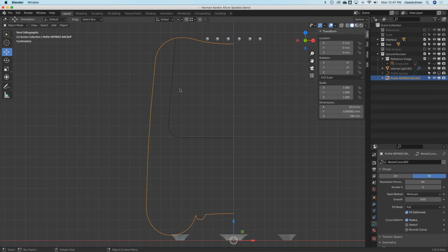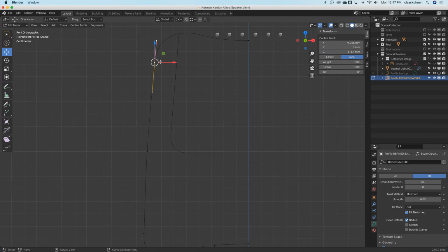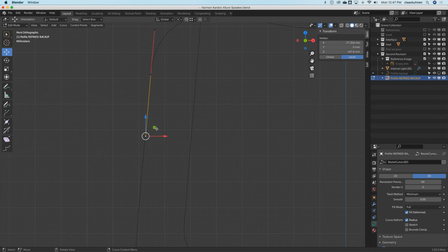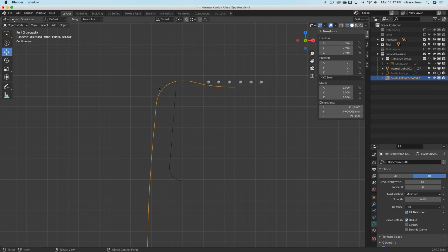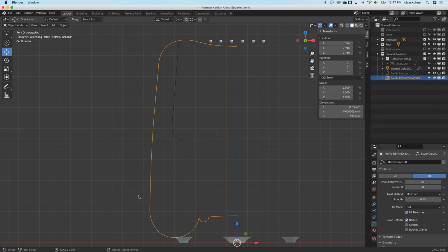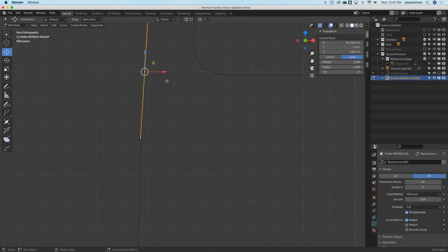Good, actually, I didn't do this because right now, seeing it from the side, I noticed there is one possible other problem. You see, this handles actually to the inside. That means the surface is kind of like going concave and then it goes convex. And you can see this here and here. Some of the handles we need to adjust. So this we will select V and say aligned. You see now it's red and aligned. That is good. And then this one here we say aligned to.